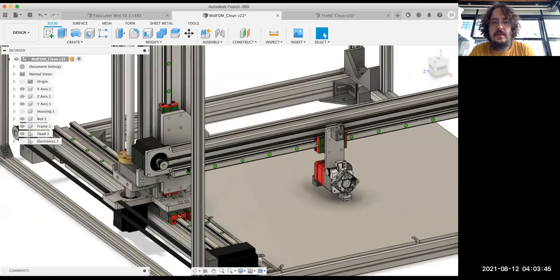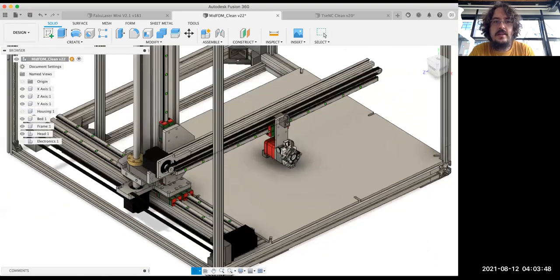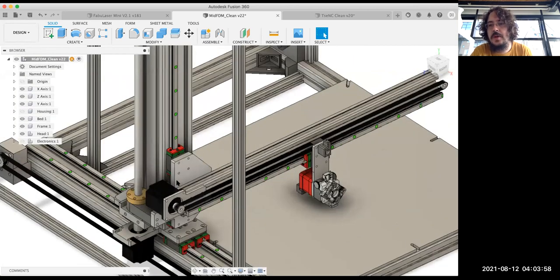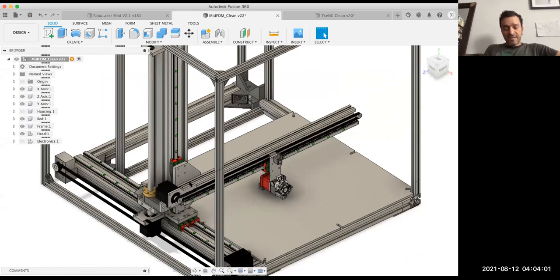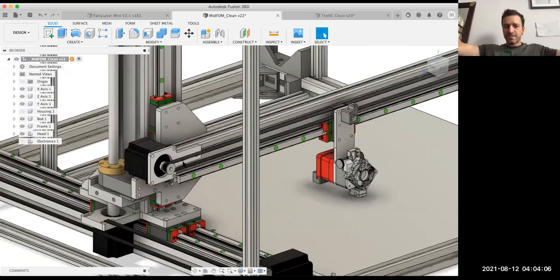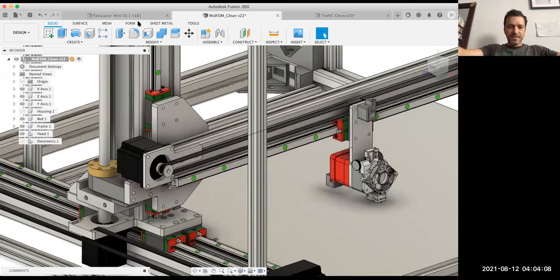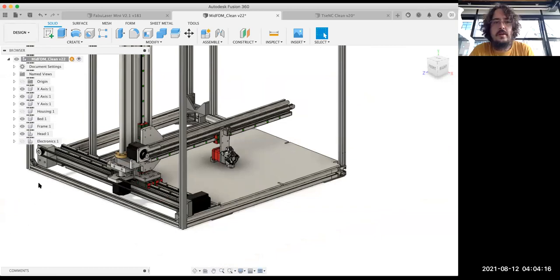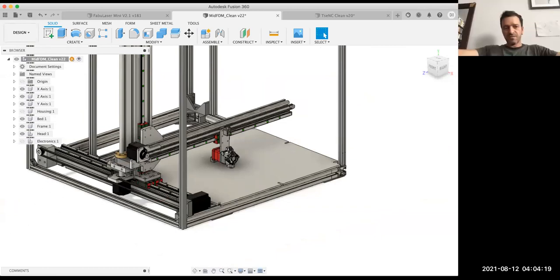Yep. No, we haven't tried that yet, but we have made this axis, this profile, rather heavy. We have made this part the heaviest of the machine. But yeah, we should still try to play with some weight. Because what I understand of the crane technology is, you see the big cranes on the building areas, they have these counterweights on the back part to reduce, you know, either the energy and also the resonance. So I was thinking maybe this would help instead of trying an electronic solution.